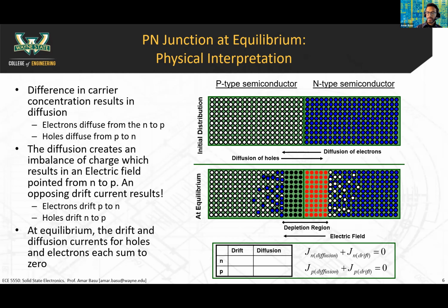This idea here is similar to what we talked about in module 4 with the concept of carrier injection. You're taking a carrier of one type and injecting it into the other side. In this case, the injection is happening through diffusion, whereas in the last module, we were injecting carriers by shining light on it.